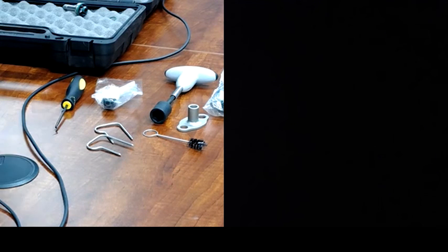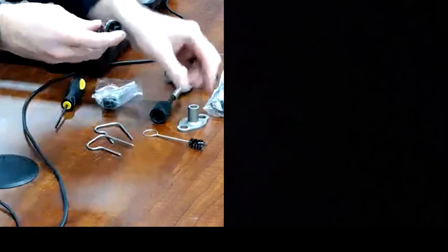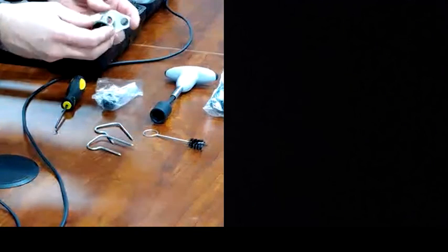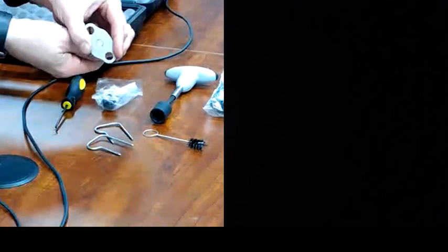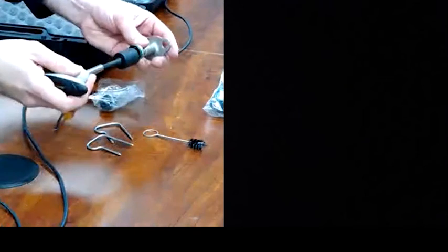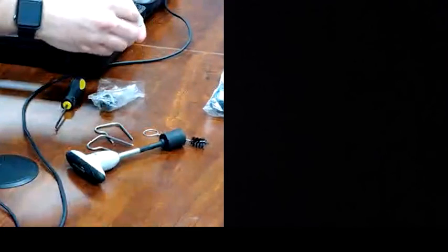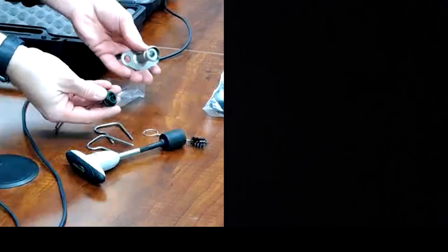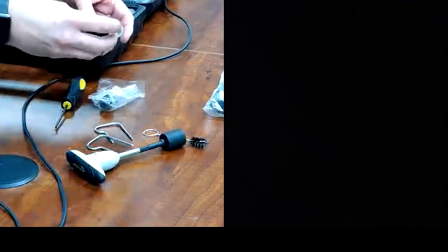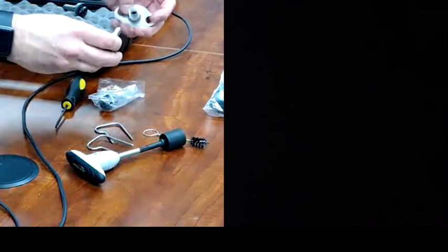So if I take a nozzle body apart again, like we did before, the instructional way that Deere recommends we do it, we take our base plate. It's keyed on the bottom, so it's going to hold that nozzle in place. Again, we don't want to use pliers on this. Using our 17 millimeter torque wrench, I can loosen that up and get to my components inside. Same way also, when I go to tighten it up, if you're out in the field and you don't have these pieces, this one's nice because it holds it in place.